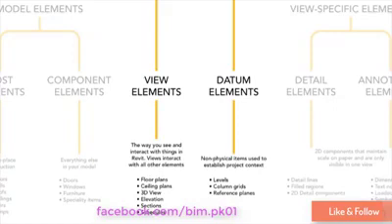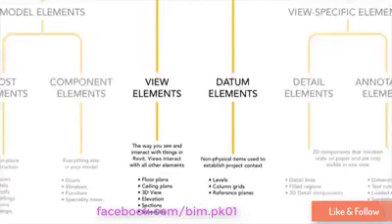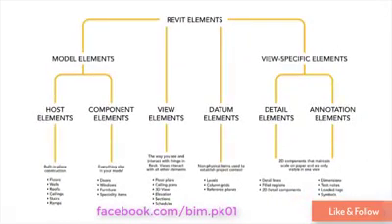However, reference planes on the datum element branch are going to be very important, and so when we get to our model families, we'll talk about that a little bit more. As we can see in this diagram, there are many different kinds of families, but only certain ones really concern us when we're talking about the family editor. And for the most part, they break into these two overall classifications of model versus annotation or view-specific families, and that will really be the focus of the majority of this training series, with the larger focus being on the model families and a small focus on the annotation families.